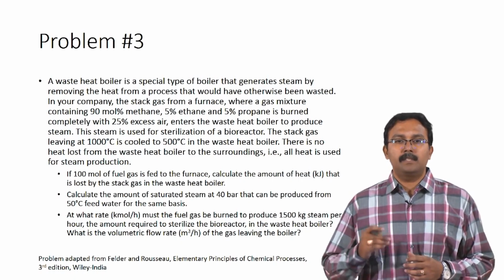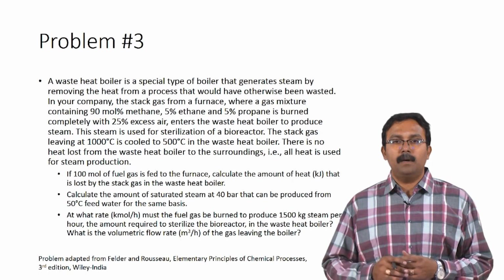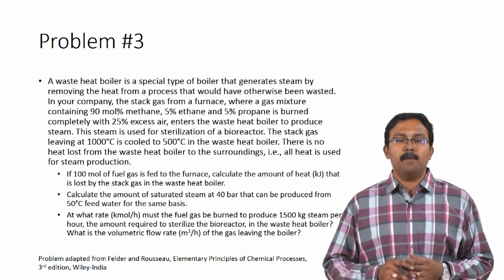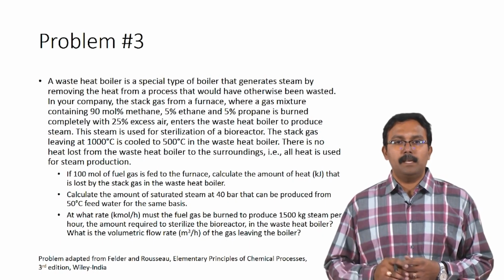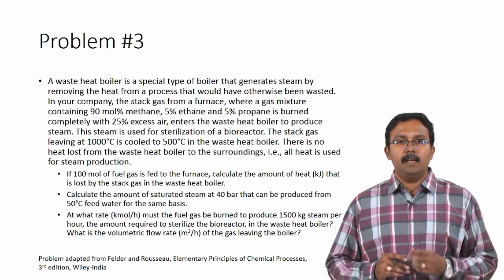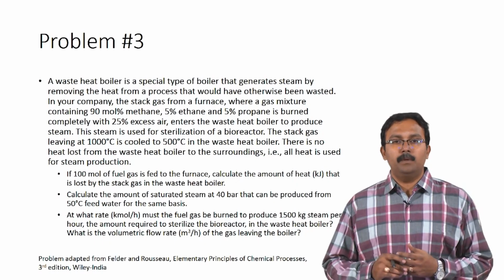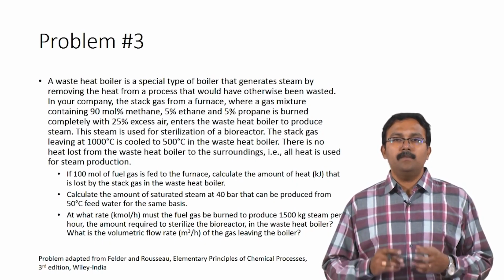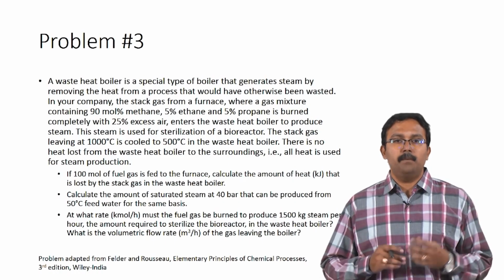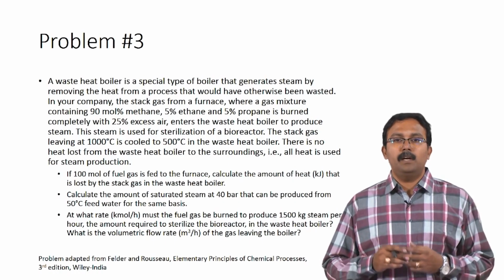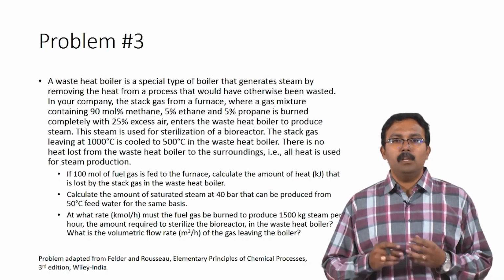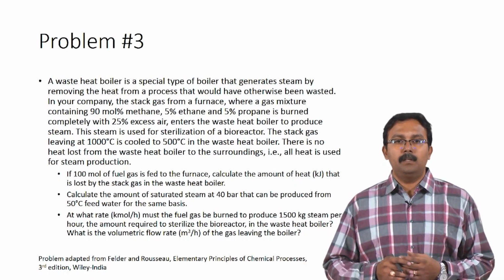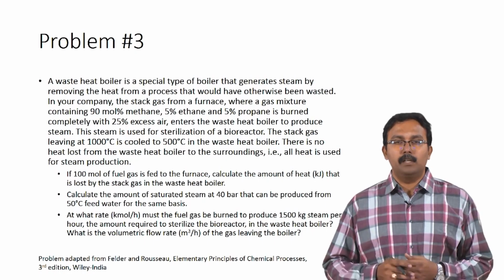Calculate the amount of saturated steam at 40 bar that can be produced from 50 degree Celsius feed water for the same basis. At what rate in kilomoles per hour must the fuel gas be burned to produce 1500 kilograms of steam per hour, the amount required to sterilize a bioreactor in the waste heat boiler? What is the volumetric flow rate in meter cube per hour of the gas leaving the boiler?